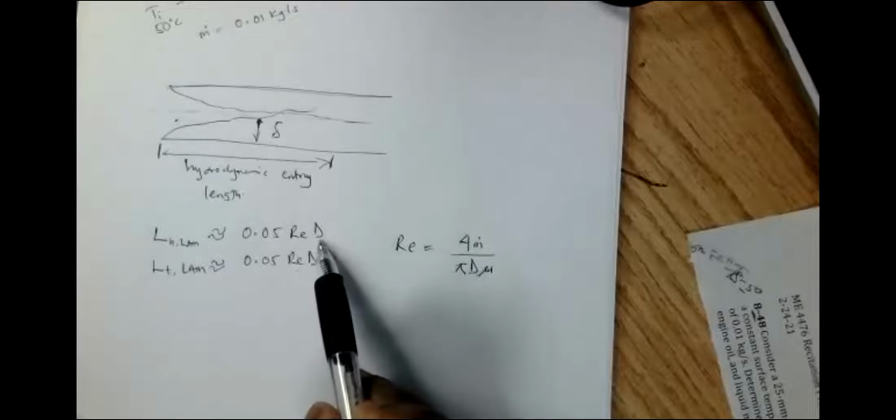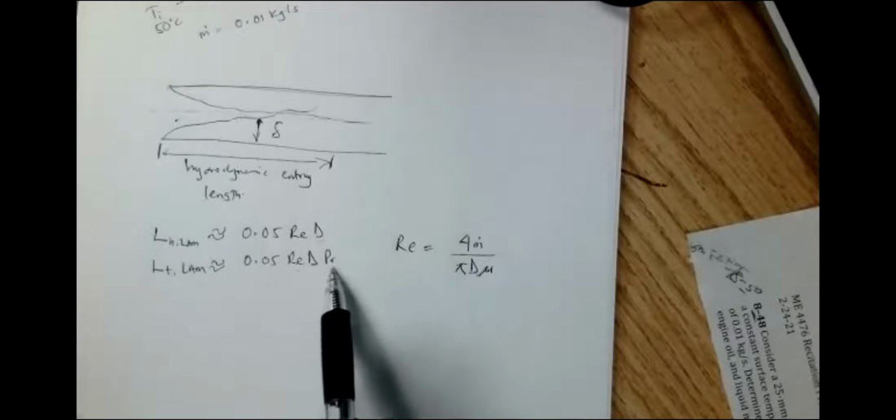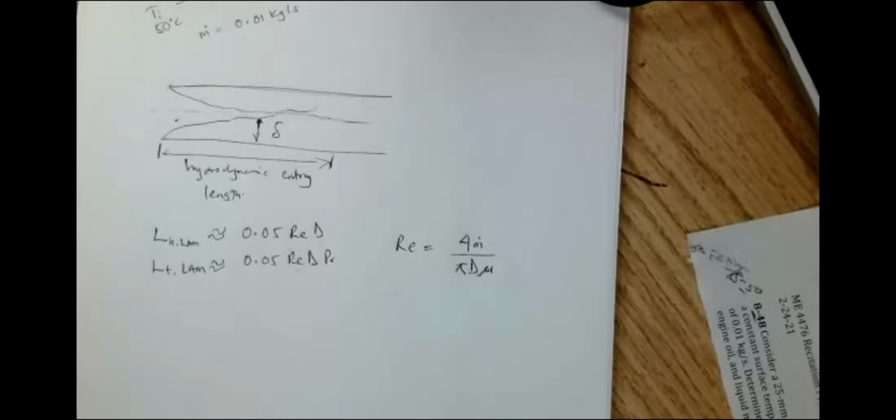We already know what the diameter is. We can find the Prandtl number from the table of properties. Now, this hypothetical boundary layer that we're considering exists somewhere in our tube, but we can't tell exactly where it is, but we can approximate it. Okay, and we can do that by finding the bulk mean temperature, right?